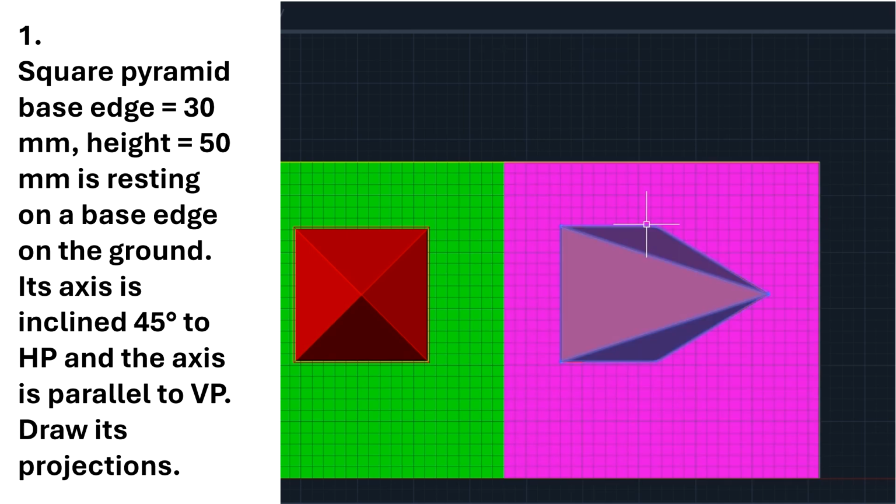You can mark all the outside edges, and this triangle also will be visible. Then what is not visible, which is below the line, that is this edge. So this is C and D, so CD will be represented with the dotted line. So this is how it will appear in the final view 4.